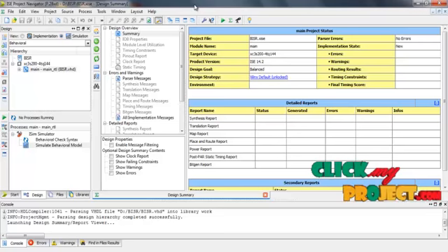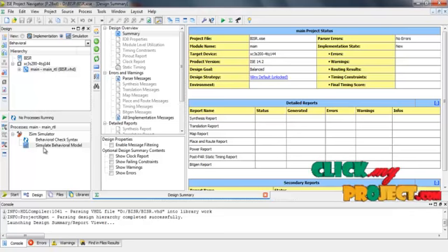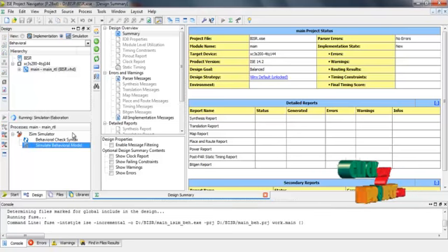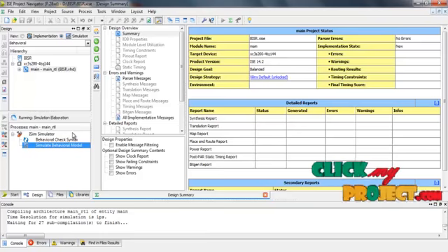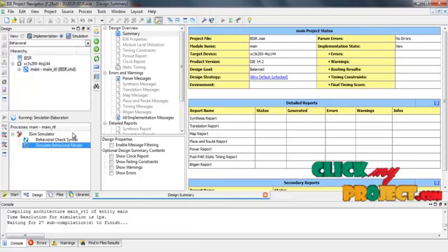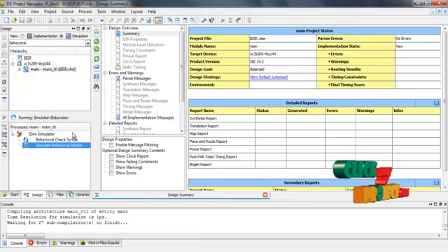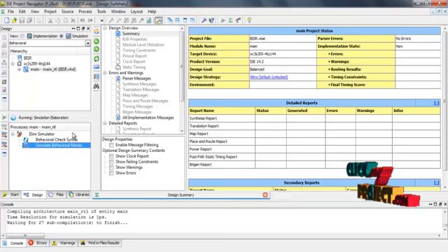To simulate the program, we have to click on simulation and then on the main icon and then on simulate behavioral model. We will see the simulation in the iSim. We have to give the inputs from where it is mentioned. The simulation is based on the inputs and the expected output will be shown.